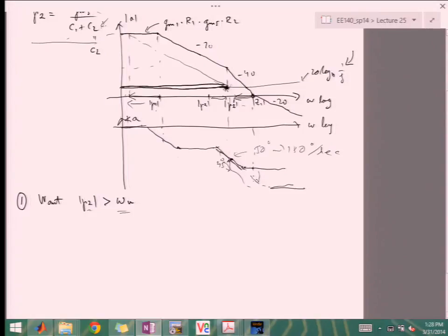The amplifier itself would look like this, up to pole 2 and then go down. So if we push our P2 greater than this crossover, the worst possible crossover with unity gain, then we're ensuring that we have at least a chance at getting a 45-degree phase margin.